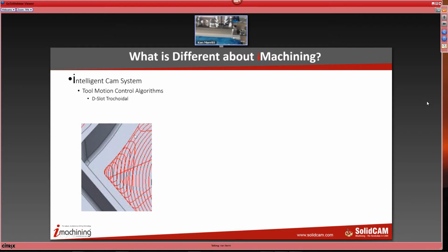Let's take this cut line right here, and walk the tool through this cut line, and you'll notice that as it gets down to this edge here, it goes into a tangent helical move where it actually lifts off the floor, does a high feed rate repositioning move over to here, and then helixes back down in for the next cut. But notice there are no non-tangent alignments in this toolpath. Everything is being done in a tangent motion, okay?